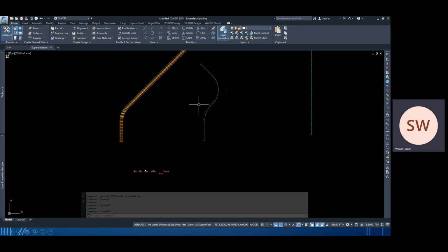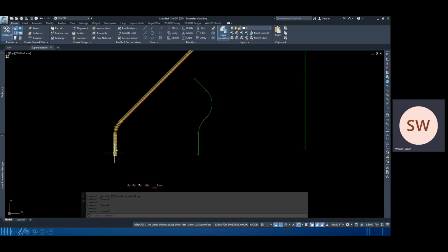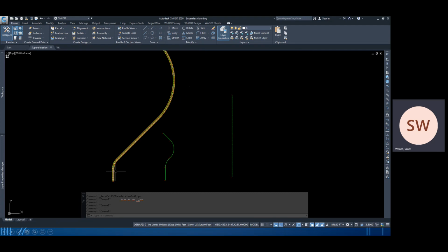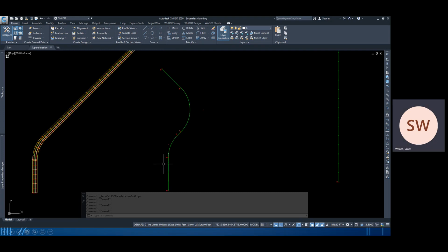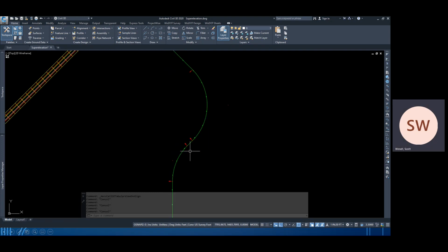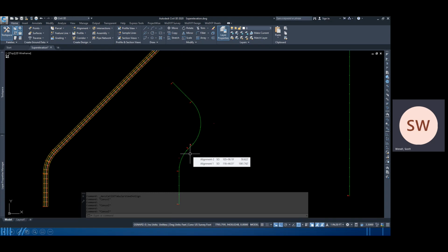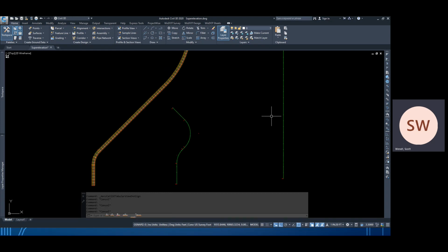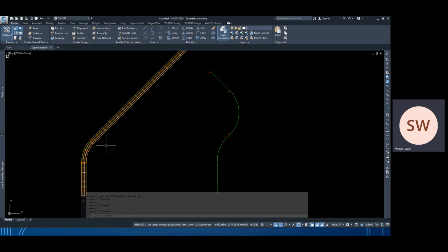So in Civil 3D here, you can see I have a couple alignments created. I have a reverse curve alignment, the corridor applied right now, with a long tangent section in between, so that the runouts between curves don't overlap. I have a smaller runout section on a reverse curve, and we're going to see how we handle overlapping stations with our superelevation calculations. And then I have our straight alignment.